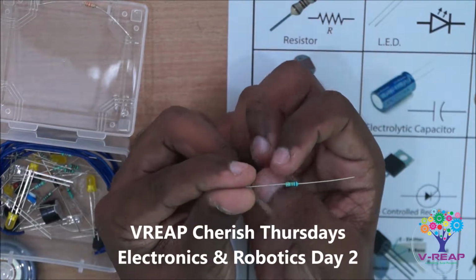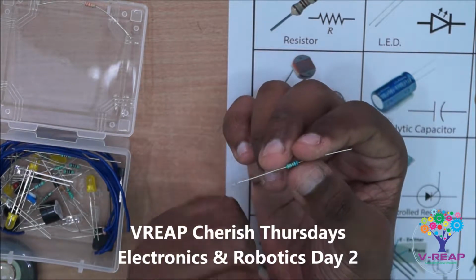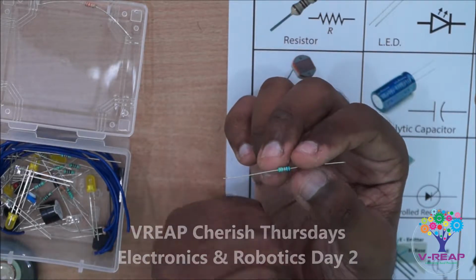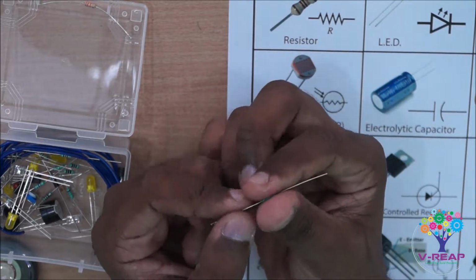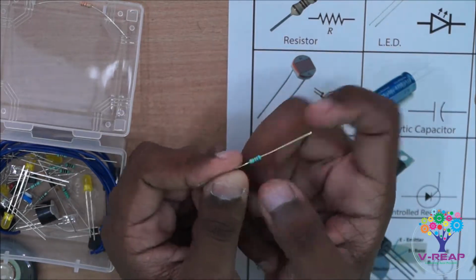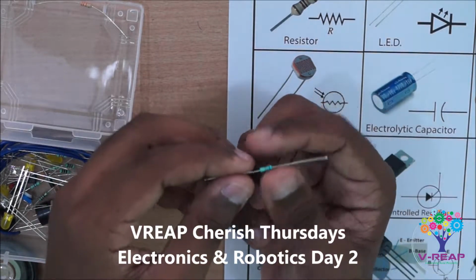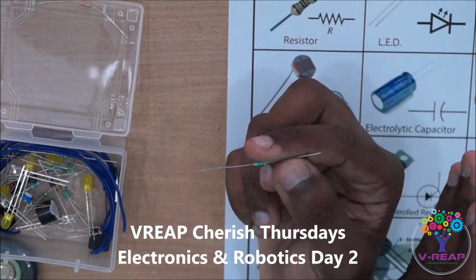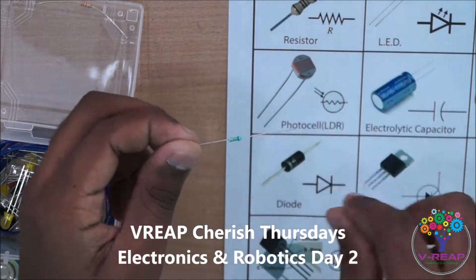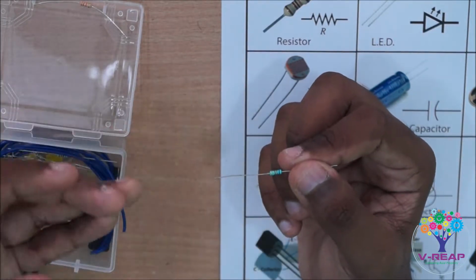This is a resistor. A resistor is a two-terminal device which reduces the flow of current. It is also used to divide voltage and it has other uses. Fixed resistors like this have fixed resistances which only change very slightly with changes in temperature and operating voltage. Variable resistors have changing resistances. They have a variety of resistances where you can select a specific resistance by pressing a button or changing a dial. An example of a variable resistor would be a potentiometer.